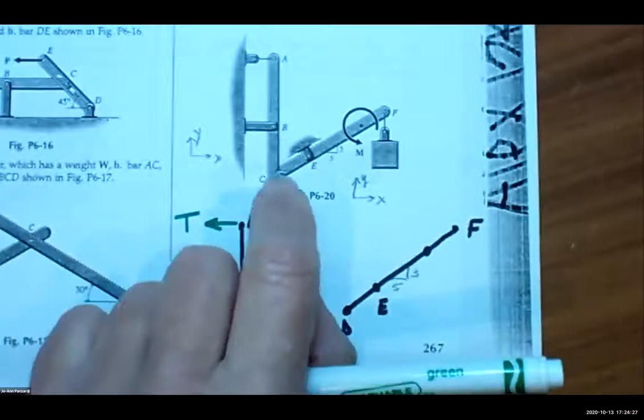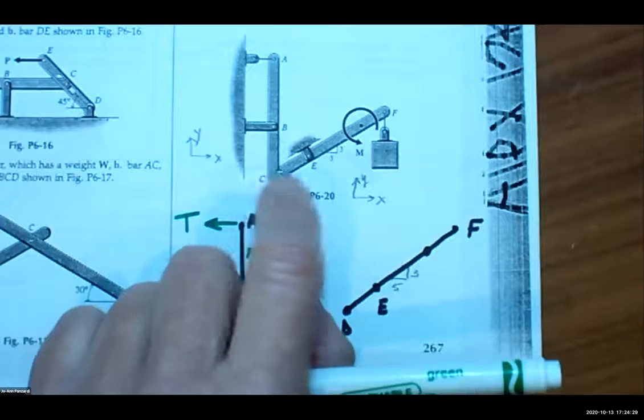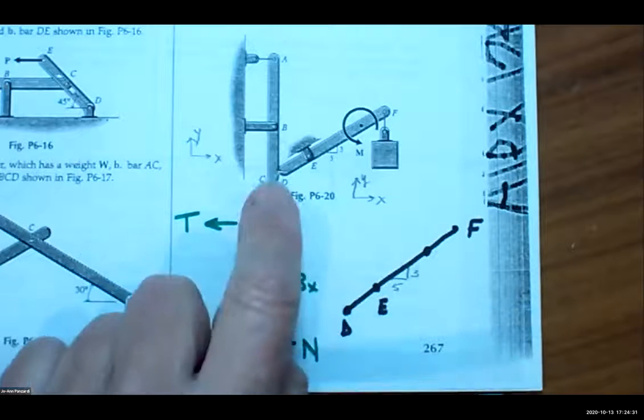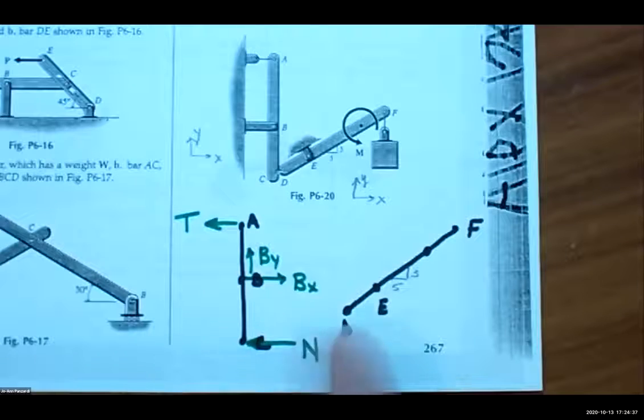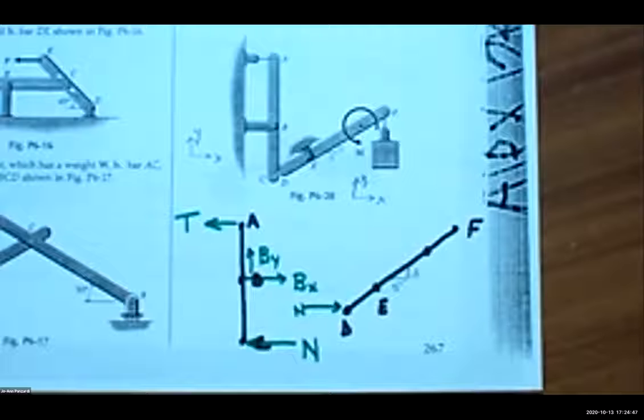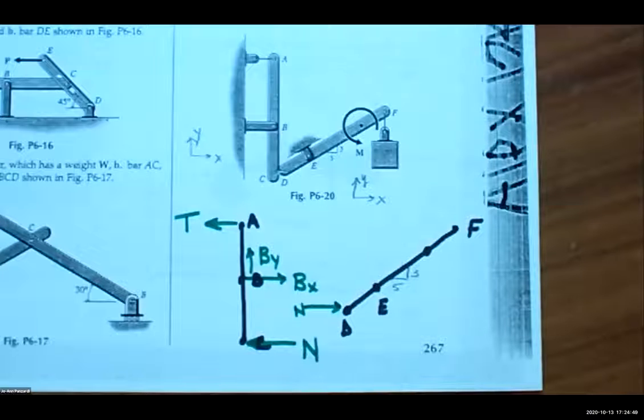I can't tell, but I think the only contact is just on C. Correct. The only thing that's happening at D and C is that they're touching each other. So on body ABC, I drew the normal from D going to the left. So what do I need to do at point D? Draw the normal coming from the left. Right. It's equal and opposite, right?